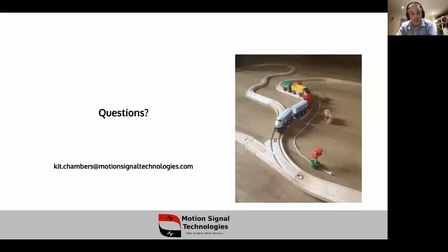Okay, so the details of that low frequency attribute are protected, so I'm not going to be drawn too much on the details of that. I'm very sorry. But in terms of what the modeling can tell us about the subsurface, I think the key is that you've got to actually understand your source before you can even look to remove it, or even know what your signals are telling you about the subsurface. Because the thing that we do know is that these signals are created by moving vehicles, and we know that that information is propagating through the subsurface to our sensors.